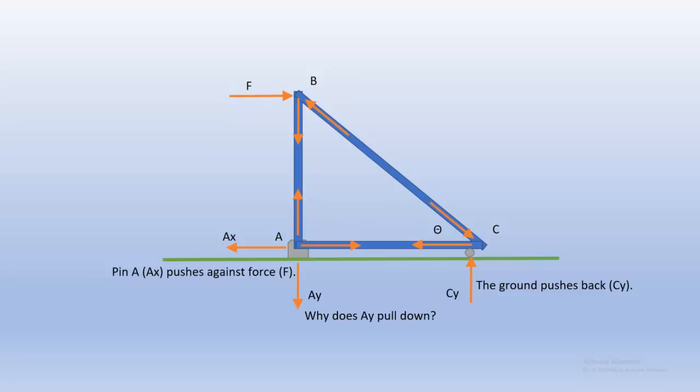If a beam, let's mention this, if a beam is either in compression or tension at one point, it has to be in compression or tension at the other point as well. So if we take a look at AC, the beam BC trying to push out, the beam AC is pulling back at point C, therefore it has to start pulling at point A too. So you see AX is equal and opposite to AC. The force at F